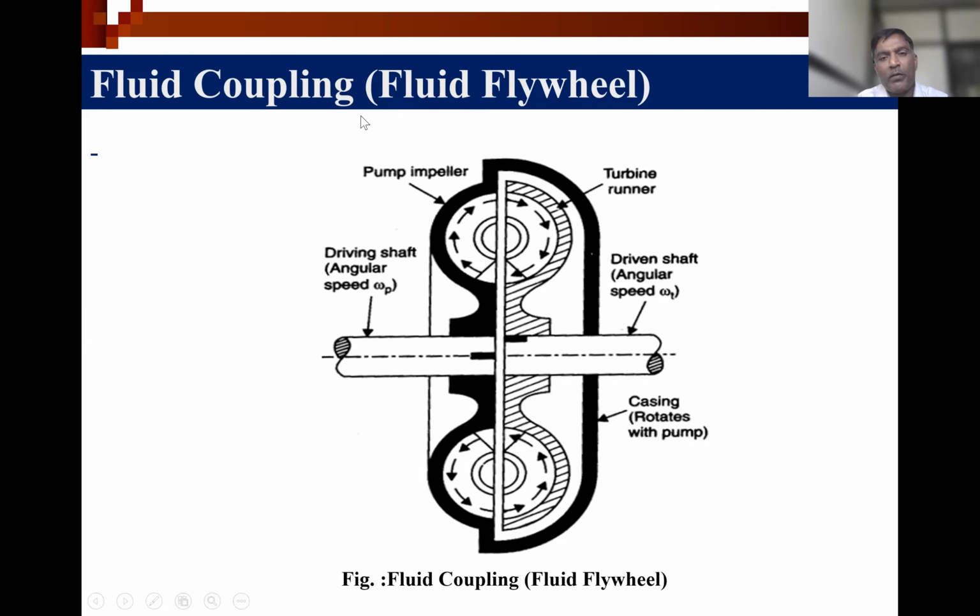In the types of clutch we have seen previously, there are 3 elements in the clutch assembly: flywheel, pressure plate, and friction plate. We drive that friction plate to get torque transmission from the flywheel to the transmission input shaft or the rest of the transmission system.